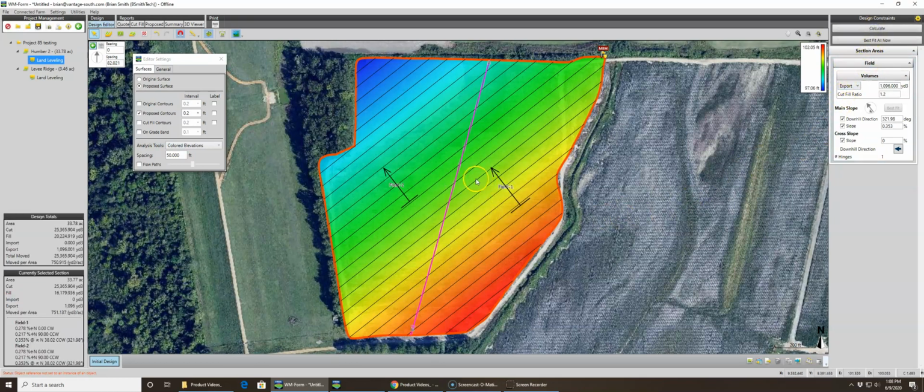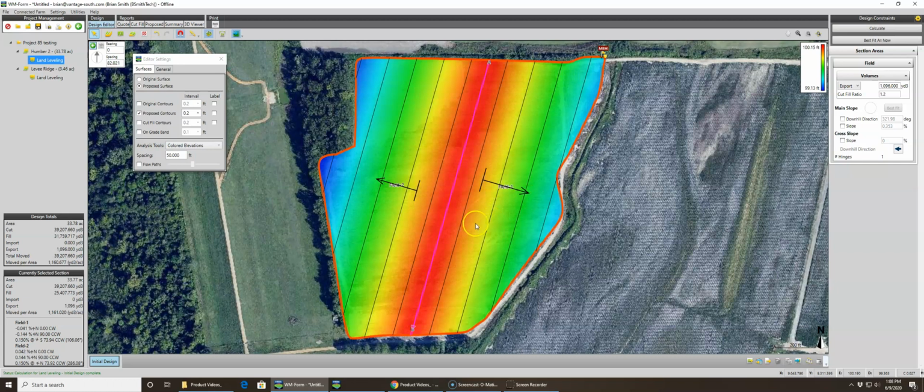Okay, there's one problem that guys say, oh, it doesn't ever do anything. Well, what you have here is you're still telling the downhill direction to go at 320 degrees. So you need to select that, hit calculate, and there is your fixed hinge. Be sure that these are not selected whenever you're doing a fixed hinge. Then of course the rest of these are all about the same. You can delete section lines, you can add a ditch, which I haven't played with much, it's quite simple to do. And then exclusion zones, and we'll get into that in the next videos.